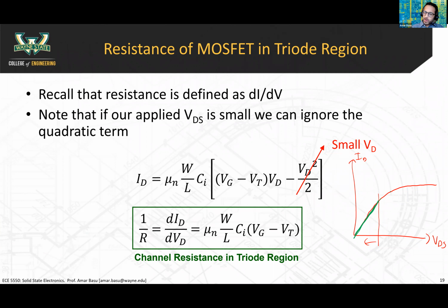And then why does this part look like this? So I'm going to say this is the linear region. This is where the current voltage characteristic is linear. And then this region here is where the current voltage characteristic looks more like an inverse parabola. So this is where that squared term becomes significant. And then everything out here, we're not talking about this yet, but this is the saturation mode, saturation region.